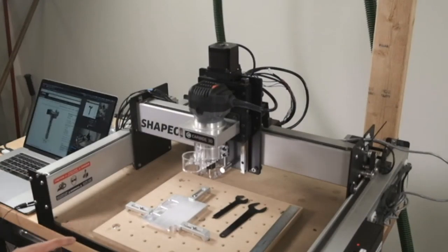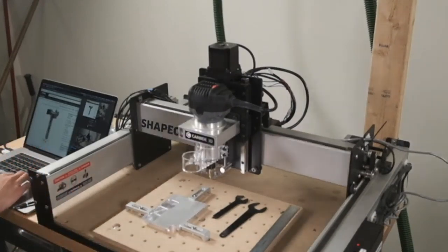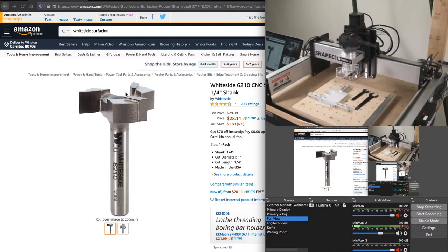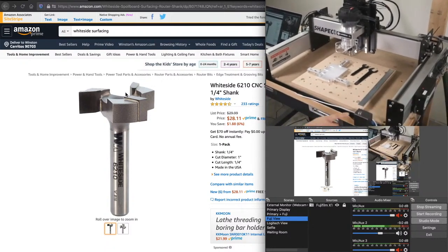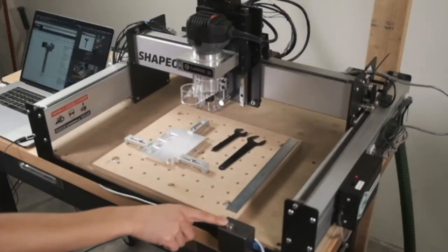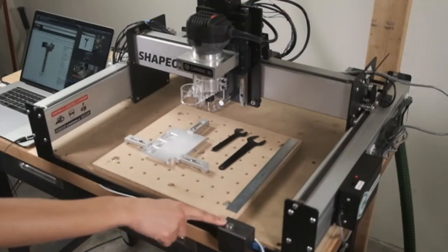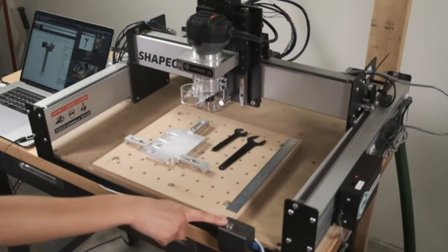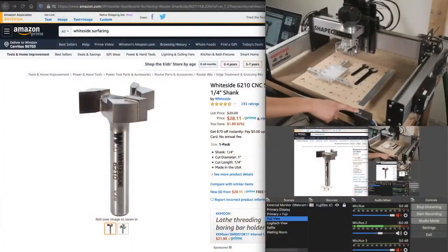They will work. Actually let me flip back to this. In the center of that tool, there is a recess, and it will just barely touch the outside edges of the bit setter. So there's a little pin on the bit setter that the tool touches off of. The diameter of the pin is large enough that it shouldn't fall between the teeth of the cutter.